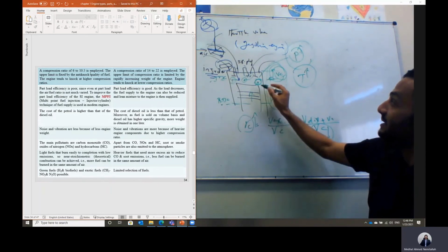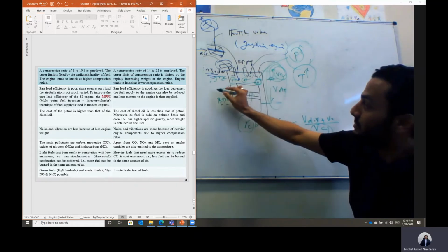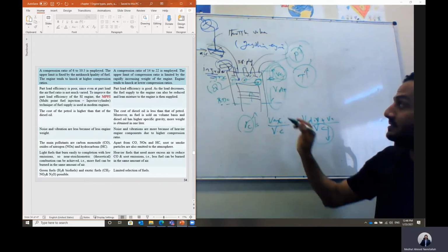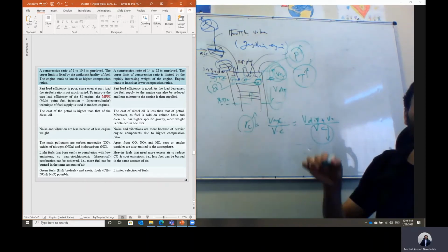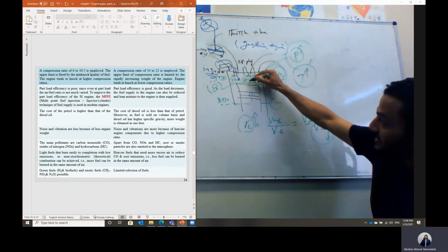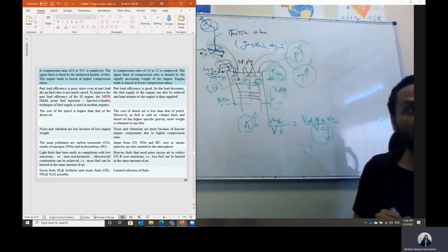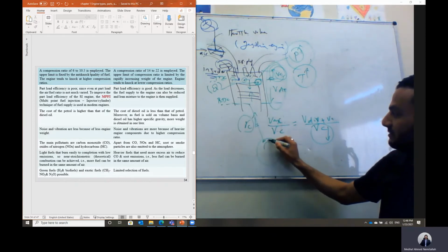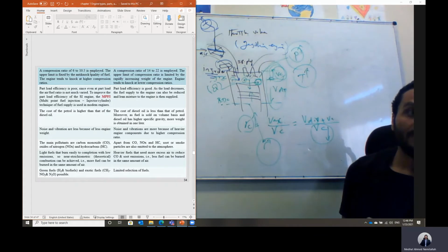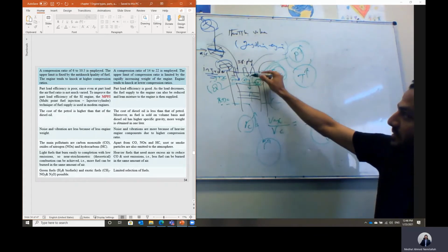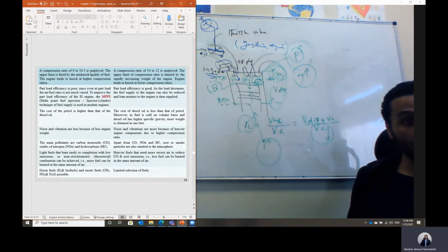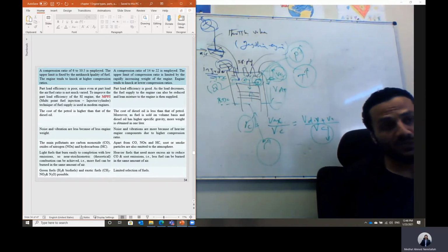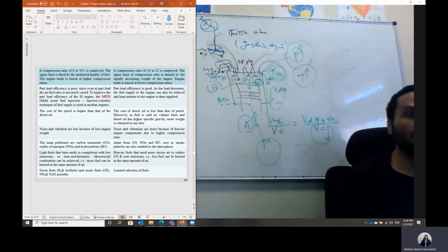Because in this case, when self-ignition starts while the piston is moving up, some heat, we call it Q, will be released. And in this case, the pressure inside the cylinder will rise. So this heat release will try to push the piston down. But the piston is moving up. This piston is connected to the crankshaft, and the crankshaft is rotating, so the piston should be moving up. So in this case, we lose part of the heat in resistance during the compression stroke. Then only a small portion of this heat will be used during the expansion or power stroke. So it causes a power loss of the engine.